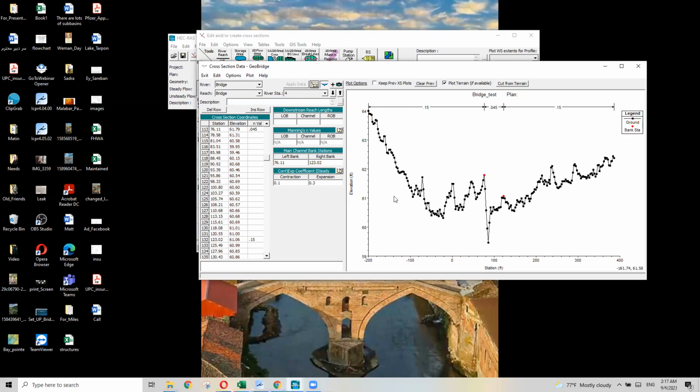Lots of people ask me how you set this up. We need to look at our aerial map. We need to know our land use, and sometimes even if your main channel is smooth, you're still using a bigger value here because you have shallower flow. Not always, but most of the time. When you have shallower flow, your manning value should be bigger. That's why I'm using the bigger values here.